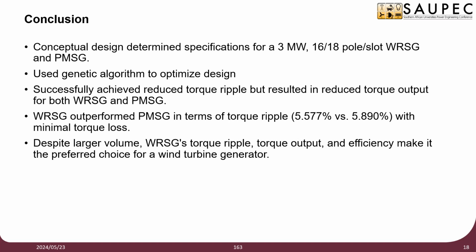Implementation of the conceptual design into ANSYS Maxwell allowed for finite element analysis, FEA, confirming the design process to the output torque being within acceptable ranges as per the design specifications. The FEA also allowed for the efficiency to be calculated by taking into account the losses in the system.